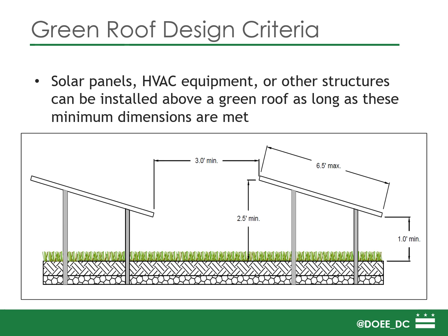This also applies to HVAC or other equipment that's an elevated structure. So you have to have that 3-foot minimum and then the 2.5-foot minimum to allow somebody to get under and perform that maintenance.